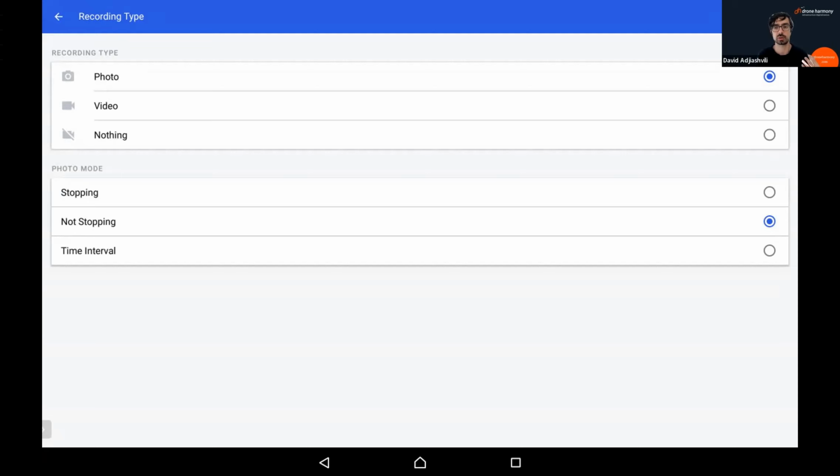If it's an image capture mode, capture the images as the drone flies through the waypoints without stopping. Of course, the advantage of the latter is that it's faster. The disadvantage is that often you get motion blur, often you get lower quality images.